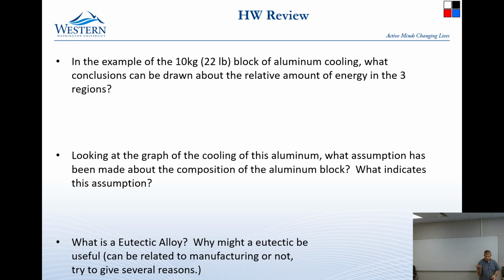And the problem is what to do when you don't want to collect heat energy, because anywhere you point it collects some amount of sun. So we normally stood them up and pointed them directly north, which is all good until the middle of the summer, when the sun actually rises and sets a little bit to the north of the east-west line.